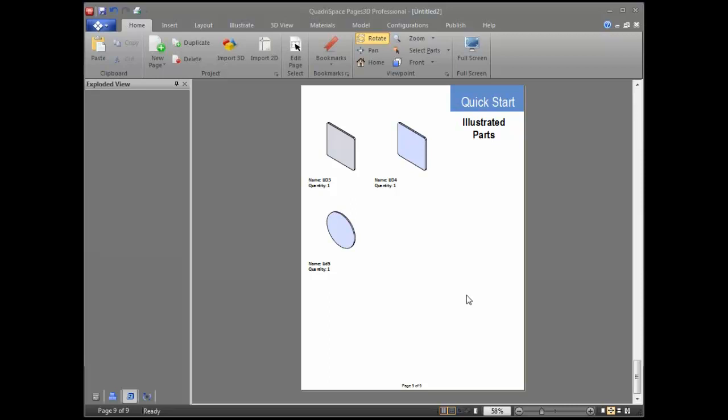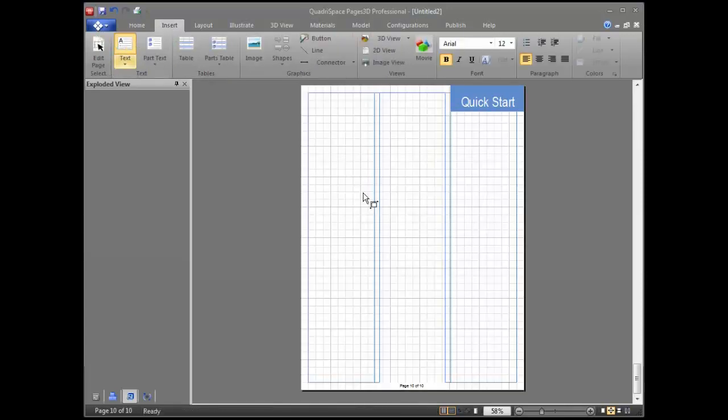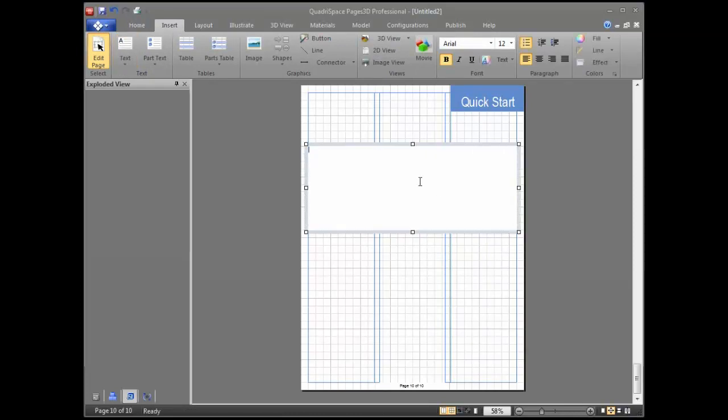The second part of this document creation process I'm going to do is take that exploded view, and we're going to automatically generate an assembly process from that. So first, let's put in a new page, and let's just put a title on here. Templates are great, but quite often you'll just have to go in and type in some of your own pages: assembly instructions.